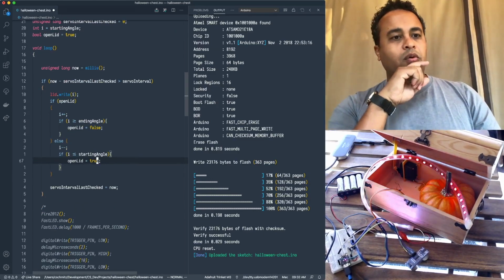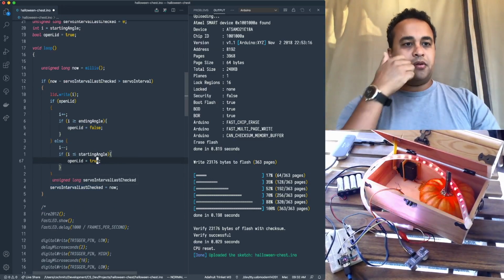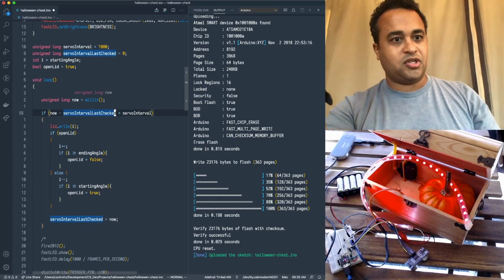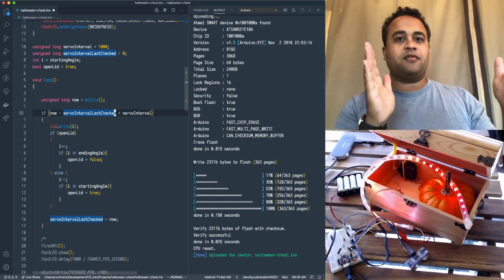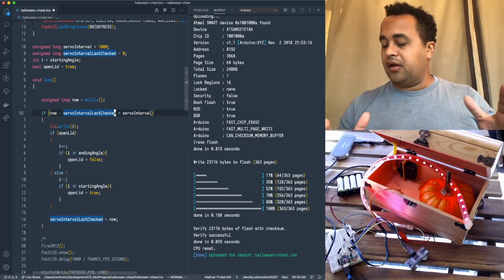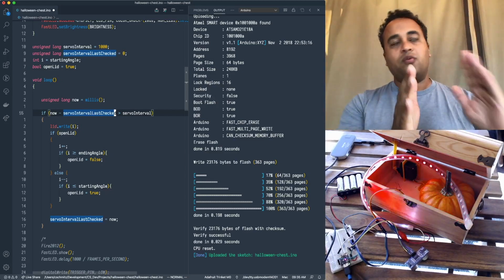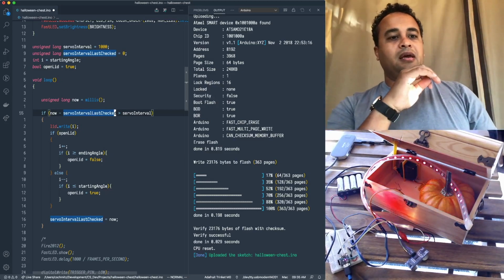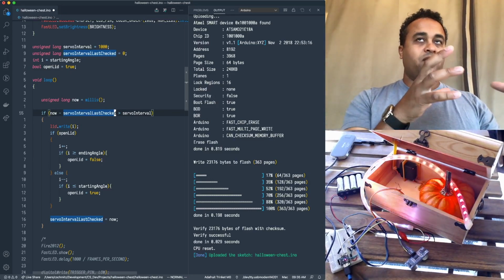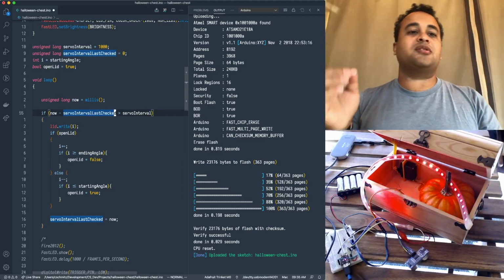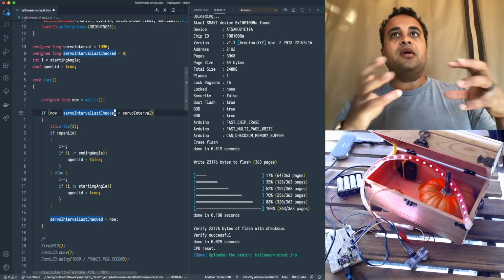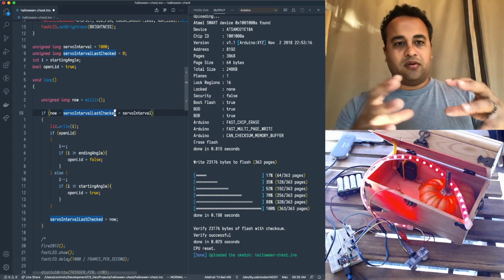Okay, so restating before we do the upload and before we do the verify to make sure that I didn't goof anything up. The way the state machine works, we grab the number of milliseconds that have passed since the Arduino has started, which means we're going to start counting 0, 1, 2, 3, 4, 5, 6, 7. And each time we go through the loop, we're going to subtract that from the last time the interval checked, which starts at 0. So 0 minus 0, 0. 1 minus 0 is 1, etc.